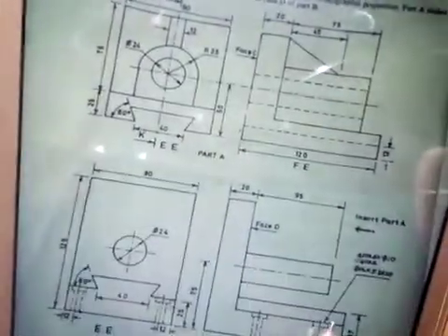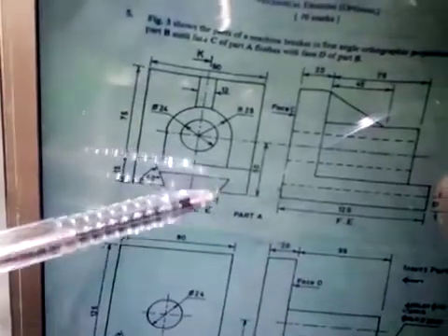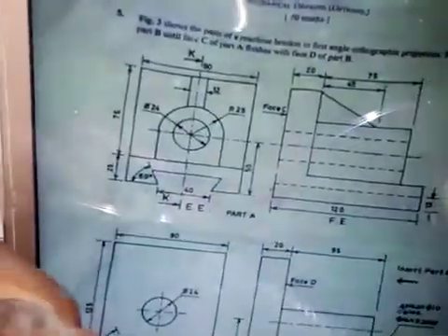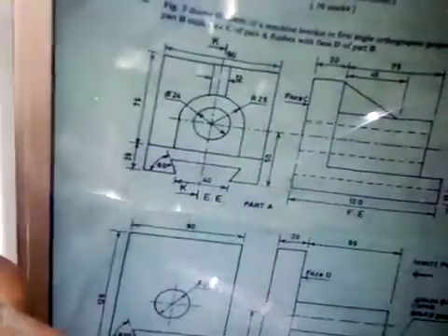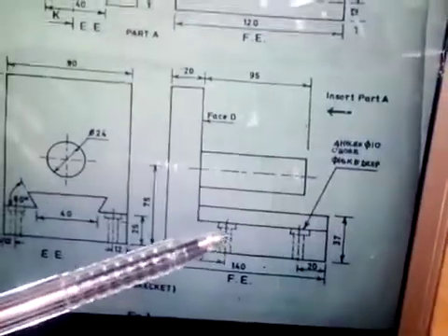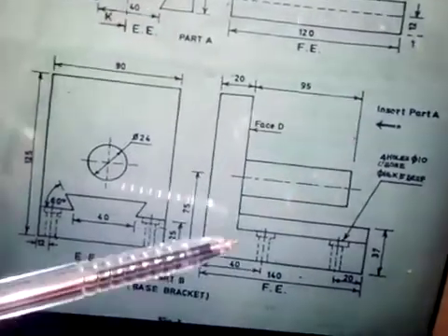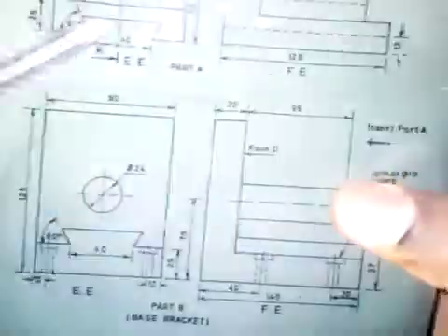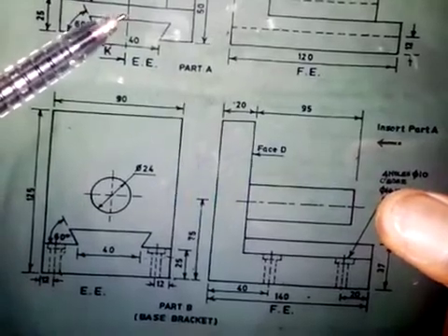So the first thing I'm going to do here is to draw this rectangle, as I said. By the time we remove this part, we are going to see this line, and the line at this point is this line that we have here, and line at this point is this line that we have here. And do not forget that we are not going to put hatching lines on this surface because the cutting plane does not touch this part, so it's going to remain unhashed. Then we produce this part, so this will also be a rectangle, as we see here.